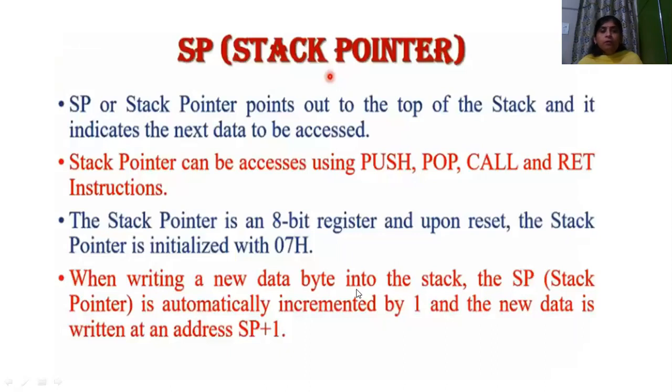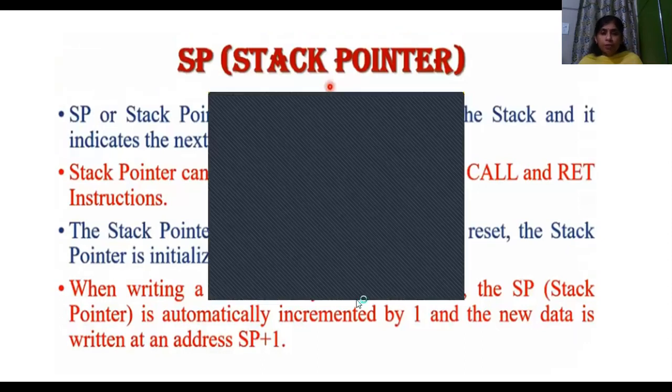Stack pointer. The stack pointer can be accessed using push, pop, call, and return instructions. It is again an 8-bit register, and the stack pointer is initialized with 07H.